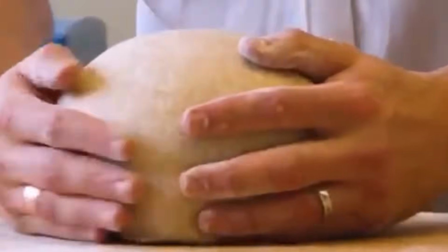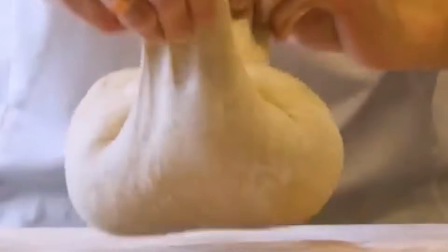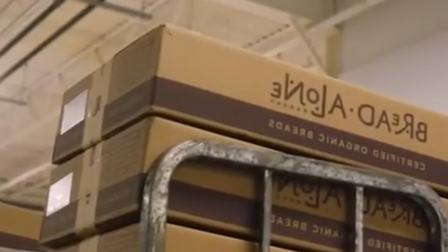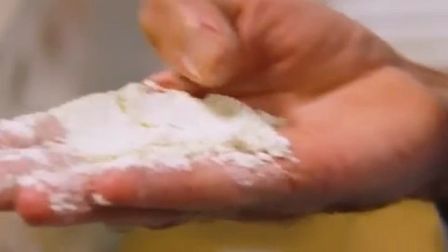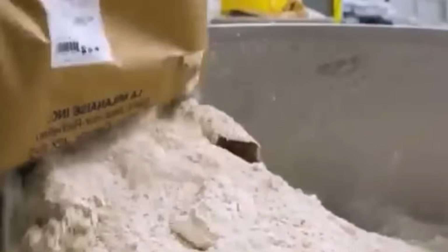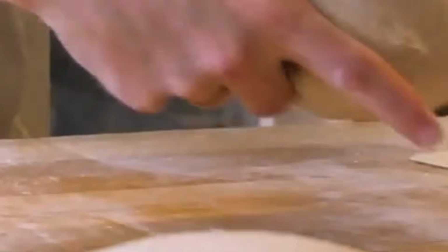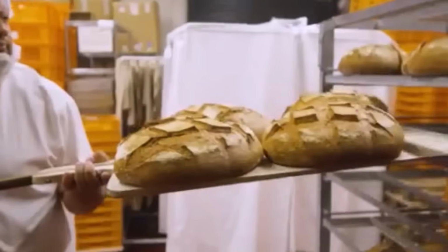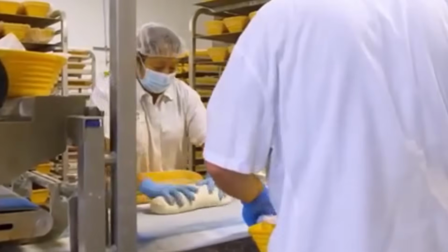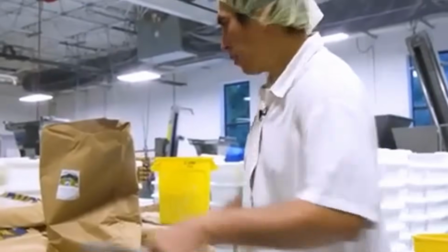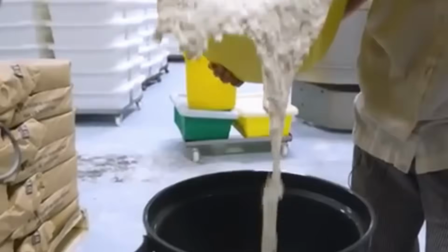Temperature sensors within the dough track the frictional heat produced during mixing, while torque sensors monitor resistance to ensure the dough reaches a consistent development profile. Cooling jackets around the mixer basin activate if necessary, keeping the dough within its ideal thermal range to avoid overproofing later in the process. Once the target consistency and elasticity are reached, soft, slightly tacky, extensible, but resilient, the dough exits the mixer through a bottom hatch, sliding as one heavy, cohesive mass into the next stage.